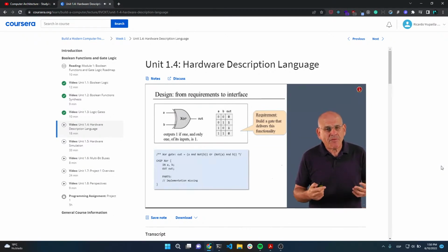And then we specify the name of the chip, the names of the inputs of the chip, and the names of the chip's output. And all this information, by the way, the name of the chip and the names of its inputs and outputs, is typically given to you. It's not something that you decide. It's something which is part of the chip's contract, if you will. So you simply write it up using the syntax, and then you write the magic word PARTS, which describes that here begins the segment of your program in which you're going to describe how this chip is actually designed.